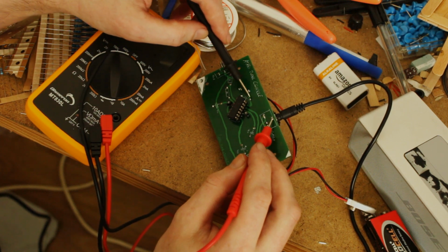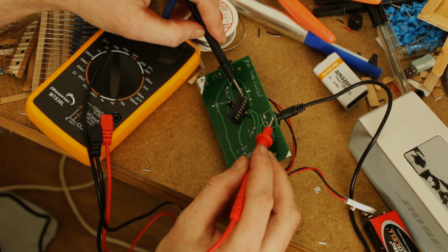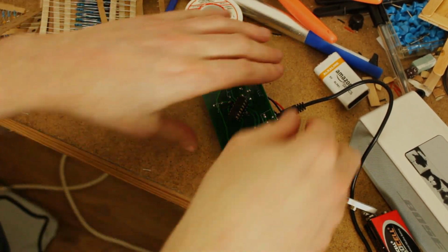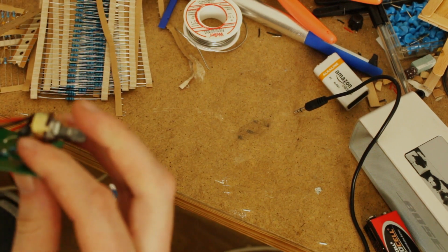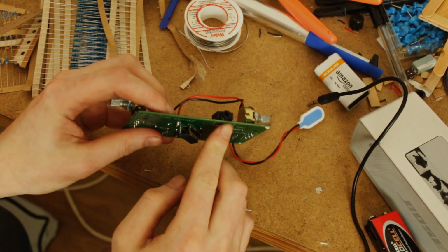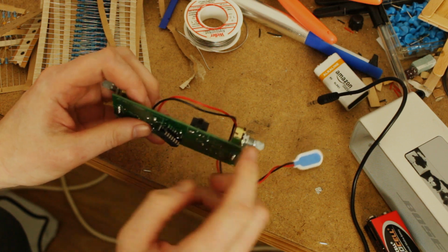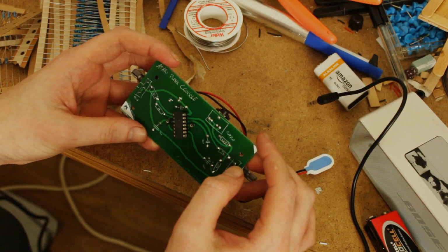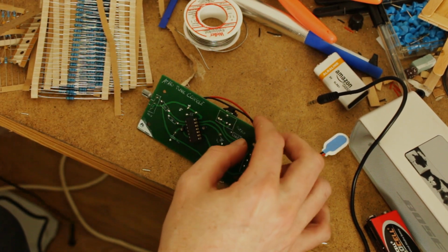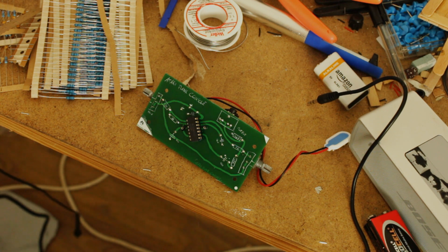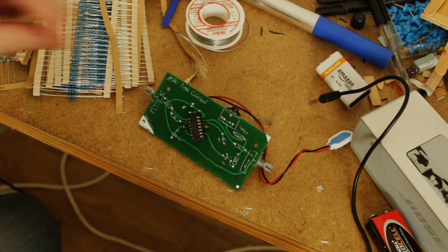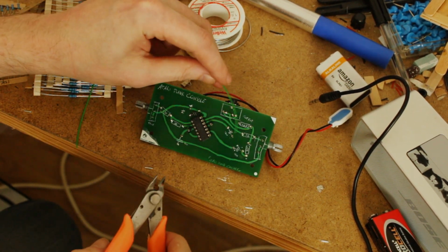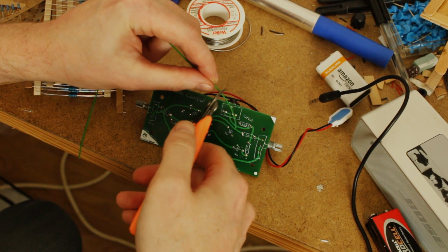Yeah, I think that's the problem. Yeah, I was afraid about that. So obviously, because I've lost my through hole there, this is no longer connected to ground. So I can fix that. I just need a little bit of a bodge wire. So what I will do is I just need to connect this ground pin up to any ground. And I'm going to guess that one right there will do.